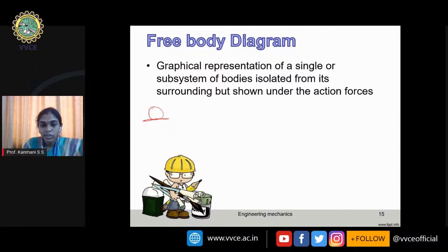It is resting on the ground, but that doesn't mean there's no force acting on it. As we saw in the previous case, if any body is said to be in the state of rest, it may undergo all sorts of forces, but the resultant should be equal to zero. On that basis, this body will have its own weight, say W. Even though it has its own weight, it's not sinking inside the earth because there is a normal reaction from the earth.